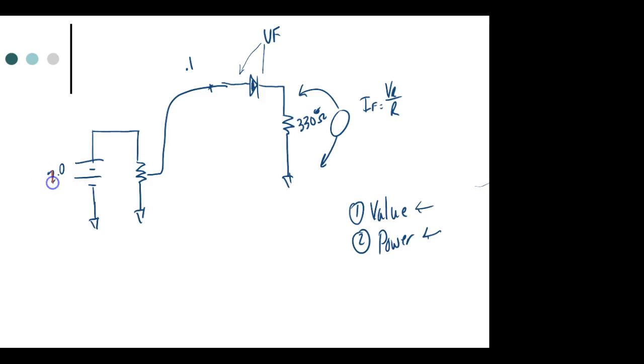So we might set it to maybe 10 volts, so now I can go from 0 to 10 volts. If I can't get 750 millivolts, I'll turn it up to more than 10 volts. That makes sense. So now I can adjust it from 0 up to 750 millivolts over here, and that's the last thing they asked for.